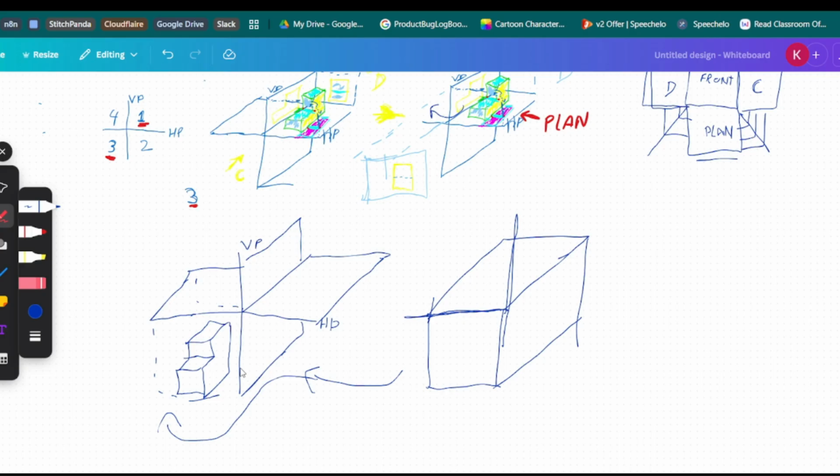If this was a mirrored surface, what you will be seeing is the details from this side of the object. If this was the mirror facing the object, then whatever details here, if it was 1, 2, 3, we'll actually see them 1, 2, 3 here. We would not see them on this side, as opposed to a flashlight, where it would be projected onto the surface. That would only apply in first angle. So I like to think about it as a mirrored surface.